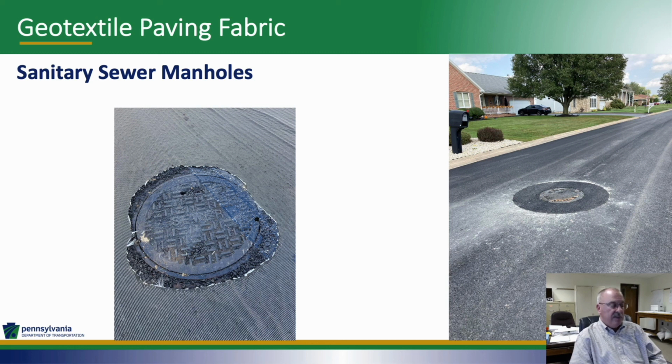We utilized a Mr. Manhole cutter that attaches to our skid steer to do this operation. And you'll see on the photo on the right hand side here how that Mr. Manhole cuts a perfect round circle, and then we're able to do the repair. Establish finish grade and raise that manhole frame and cover up to grade.